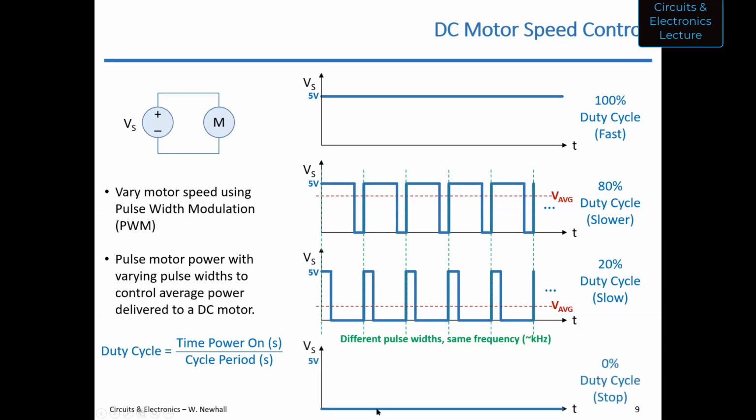And then to stop the motor, of course, you can use a 0% duty cycle, just like when you were flashing your LED or turning it off. And so you can adjust from full speed to no speed, and you could actually include this in an active control system that would feed the speed back, in other words, measure the speed back to a controller, and that way it would maintain a constant speed if you want that.